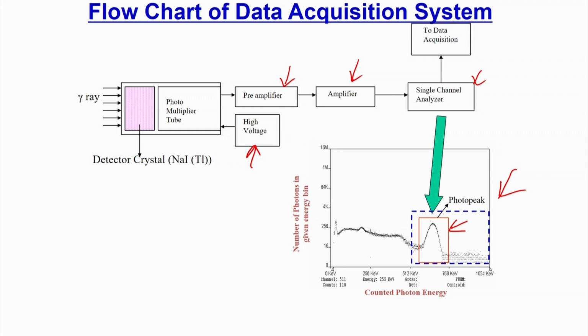So, what we do actually, is that even our tube lights are emitting photons. Now, the hardware is not able to detect the difference between that photon and a photon coming from gamma rays, other than the energy; the energy of these tube light photons will be much lower compared to the photons coming from the gamma rays. And there will be some noise also, as you know that all electronics generate some noise, and that is why we put in the pre-amplifier and amplifier, so that I can increase the signal to noise ratio. I can amplify my signal so that I can reduce the noise. Now, all these things are incident, and they are all contributing towards the count.